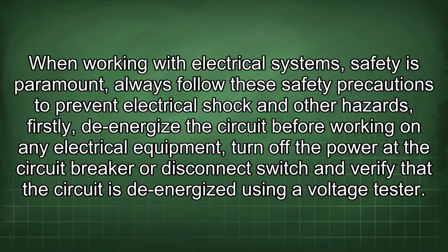When working with electrical systems, safety is paramount. Always follow these safety precautions to prevent electrical shock and other hazards. Firstly, de-energize the circuit before working on any electrical equipment. Turn off the power at the circuit breaker or disconnect switch and verify that the circuit is de-energized using a voltage tester.